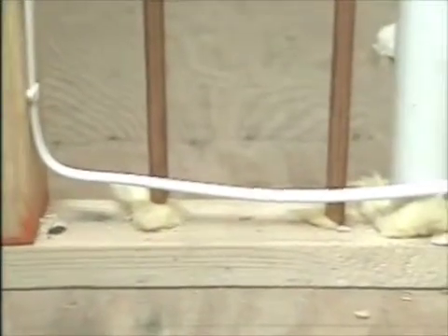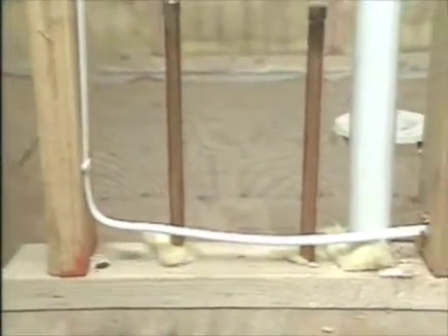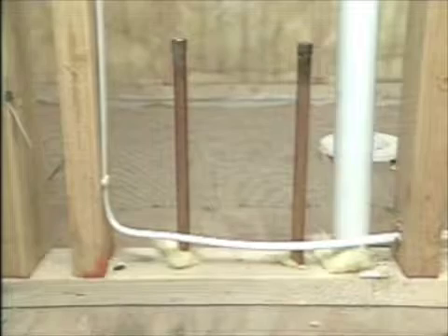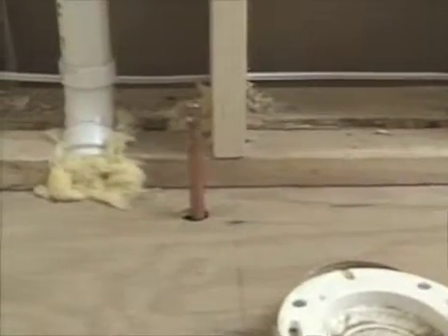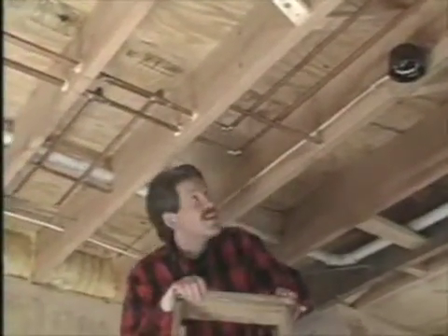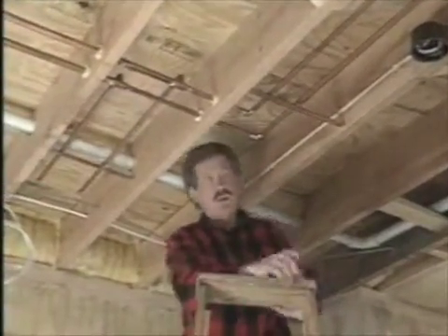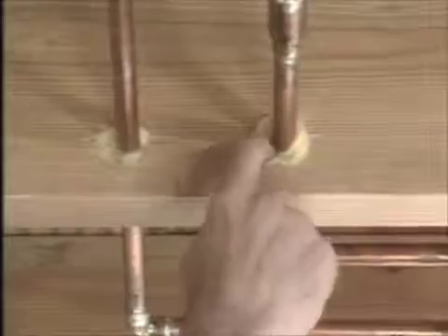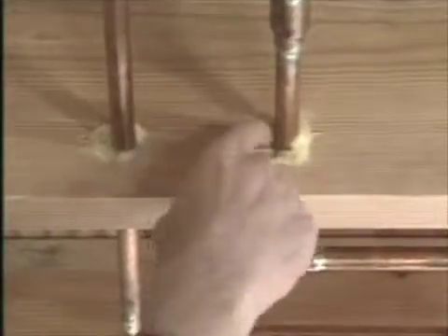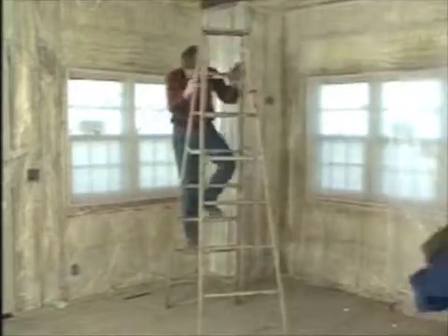The pipes usually run in pairs, with hot and cold water pipes going to fixtures like sinks and tubs. But some fixtures, like toilets, need only a single cold water pipe. The copper tubing is fairly stiff. At the same time, it still needs support on longer runs. Here you can see a piece of copper tubing has been wedged in between the 2 joists. And where the tubing goes through a hole in the joist, insulation's been stuffed in the hole to keep the pipe from rattling.